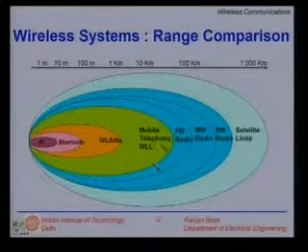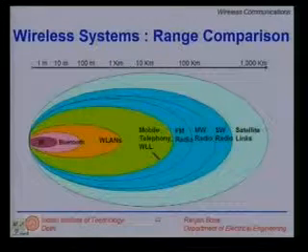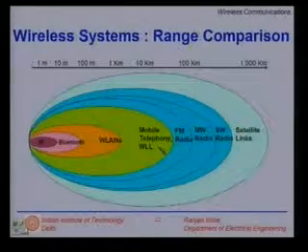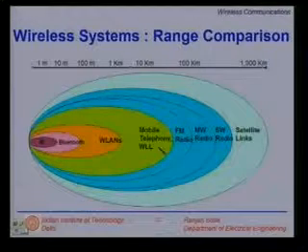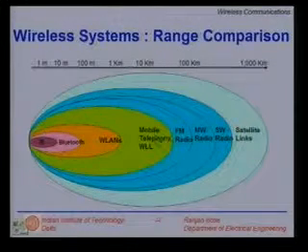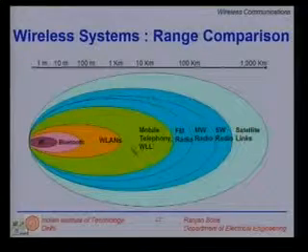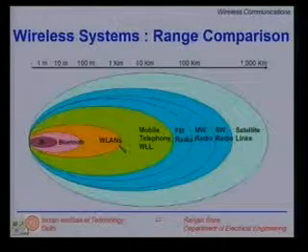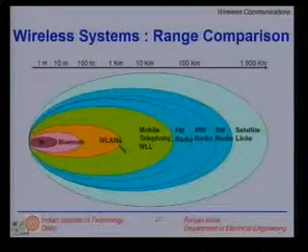The green ellipse is the mobile telephony, wireless in the local loop. We go into kilometers, at most tens of kilometers. Later we will see that the distance or the cell sizes used for cellular networks depends not only on how far the signals go, but also on a couple of other things like interference and capacity. So we will figure out what determines the size of the cell other than just the propagation issue. In this slide, we're only talking about how far the rays will travel, provided the input power is fixed at a certain level.